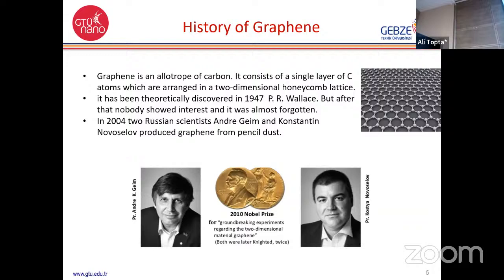To be frank, most of the fabrication techniques will give you a few layers, or they will give you a foamy type fluid. One can give you a single layer, which is CVD, chemical vapor deposition, but even CVD will give you a few layers when characterized thoroughly. So single layer graphene is still a little bit far away.